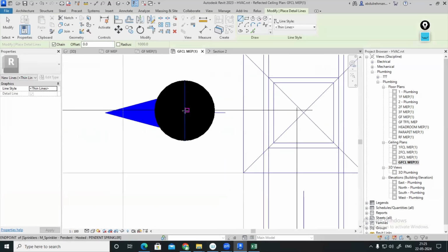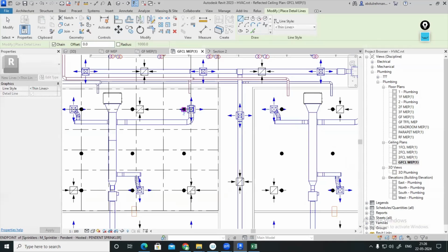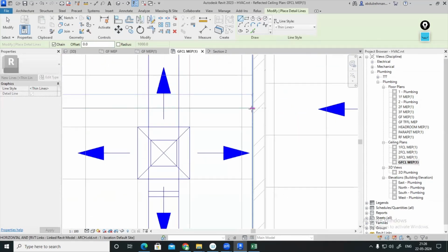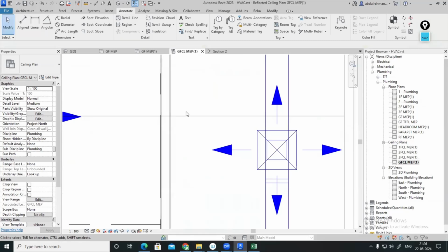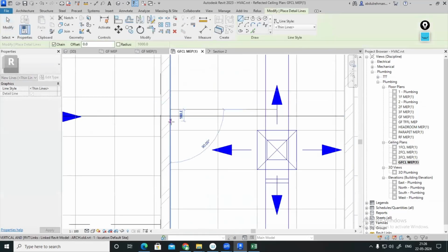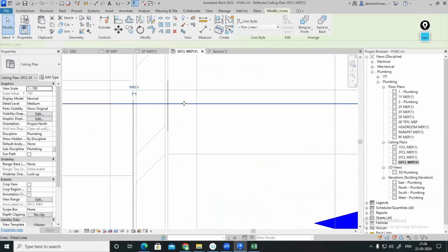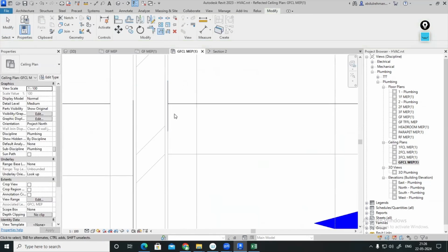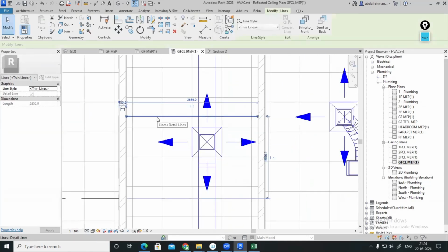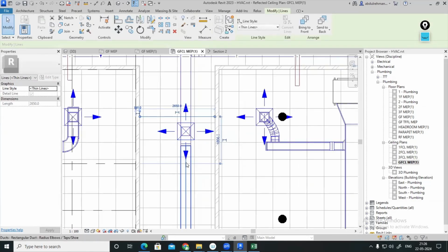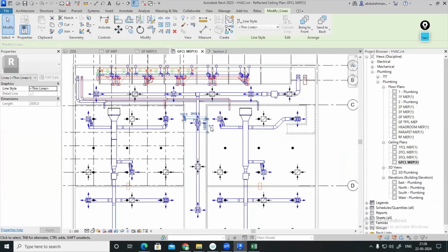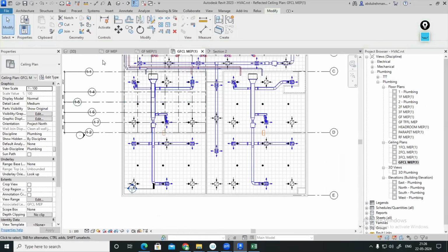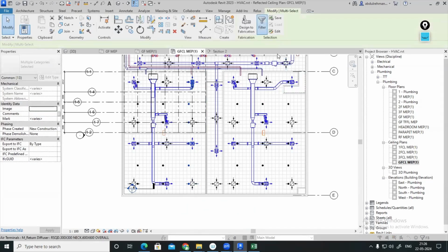Okay. In the middle, from the middle side, I'll be making a reference line. Here. Okay, like create similar. Let me make this one. Trim and extend. I need this one and this one. Okay, now the reference line I can delete. I need the center point. Select it. A center point, it is not possible. Somewhere here in the middle we can place. Okay, so let me select the sprinklers. So from this side, I'm just selecting the sprinklers. Apply. Okay.